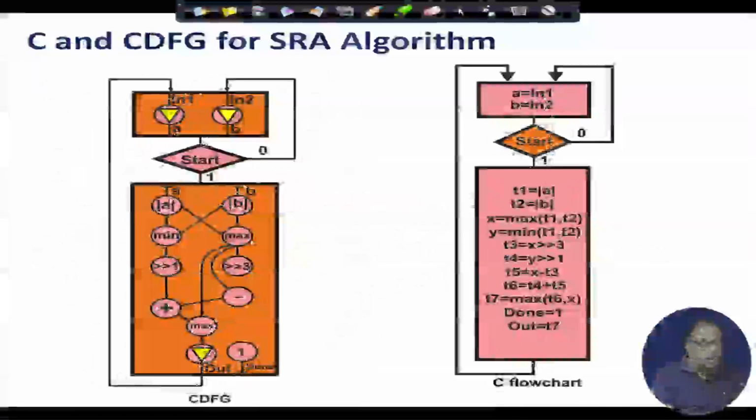So, this entire thing can be transformed into a CDFG, where I just look at the data. The variables are not shown here, you see. Here, the variables are data that are flowing along these data edges, data flow edges. The data is flowing along with these operators.